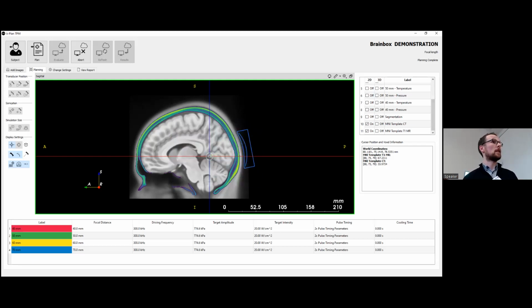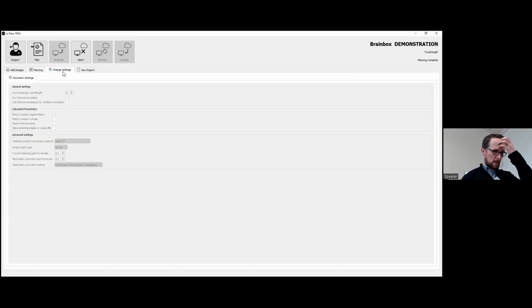The temperature profile, yeah. So that's possible in this cooling time. So that would give you your duration between sonications. That might be over several hours, depends if you have different experiments during the study, all based on the same transducer location. And you have the ability then in this part of the settings, link thermal simulations for multiple sonications. If that's ticked, then it daisy chains them on together. If it's unticked, it treats them as just separate individual sonications that you might just be comparing other parameter variables and those changes.